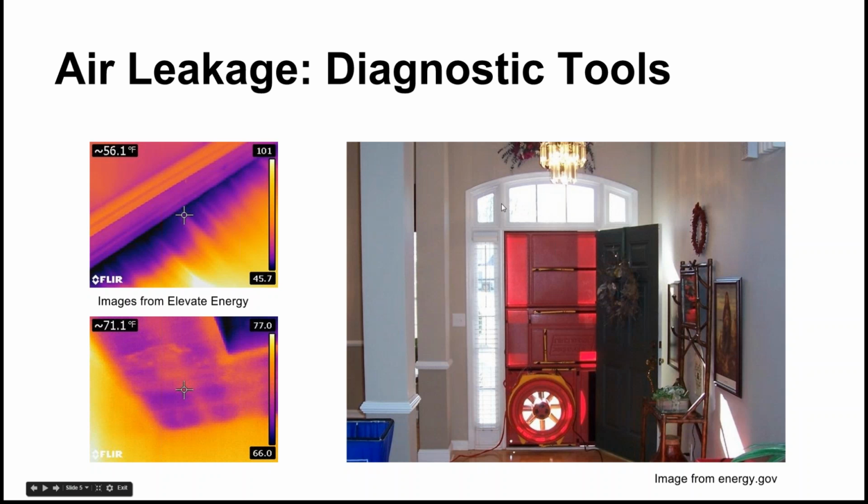And then another diagnostic tool that you probably have not heard of unless we sent a video out about it. It's called a blower door. So basically this arrangement right here is a fan that blows air out of a house. So basically it depressurizes the house by blowing air out, creating a vacuum inside. So a good analogy for this is inflating a leaky beach ball. If the beach ball has no holes, not a lot of air is required to fill it. It fills it and it stays in. But a beach ball with smaller holes would require a small but steady stream of air to keep it fully inflated, and the more holes there are, the more air is required.